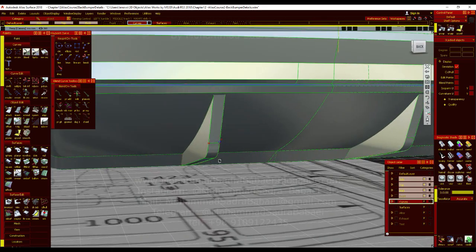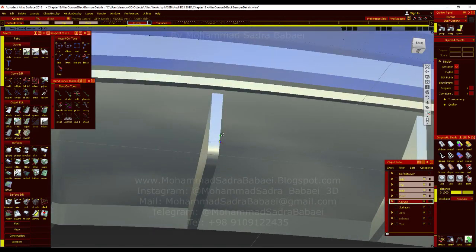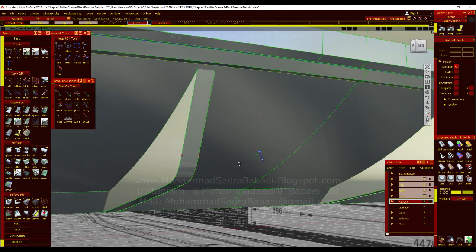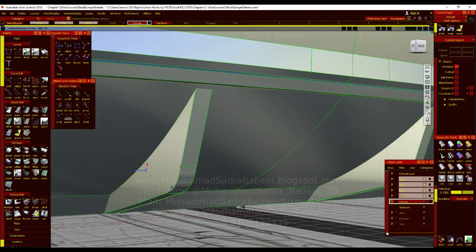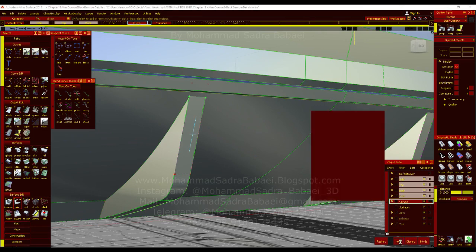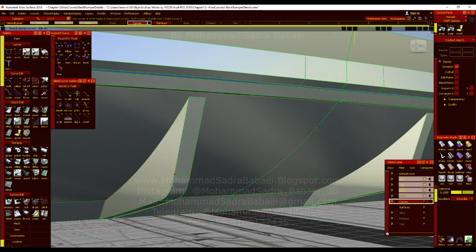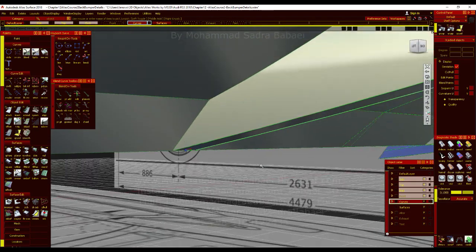You know, filleting is one of the important things in modeling section and also class A surfaces, because soft fillets are very important. You know, some good fillets. So what is the good fillet? Let me just show you with an example. Let me just intersect these surfaces and trim that, because you should intersect all the surfaces you want to go for filleting before adding a fillet.